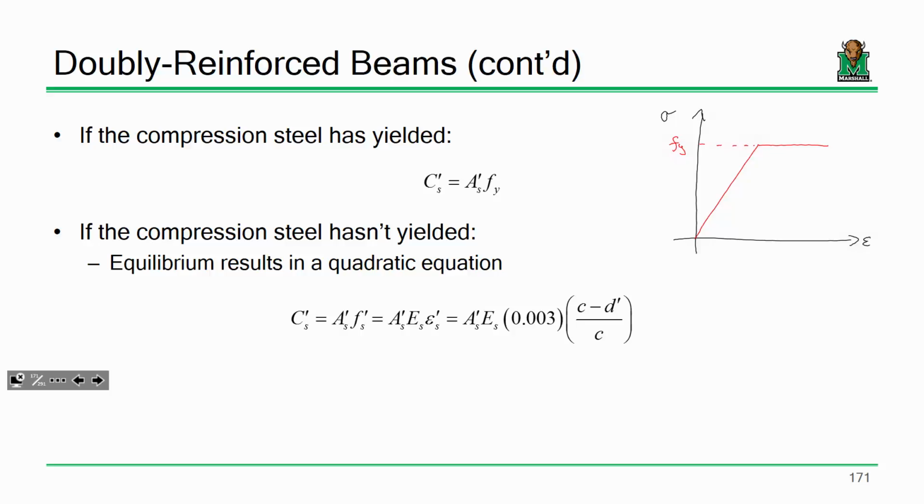So this slope is what? That's the E for the steel, right? So if my strain is lower than epsilon sub y, and I want to determine some point on this curve, some f sub s, how would I determine that? I'd say it's E times whatever the strain is. Does that make sense? Everybody okay with that?